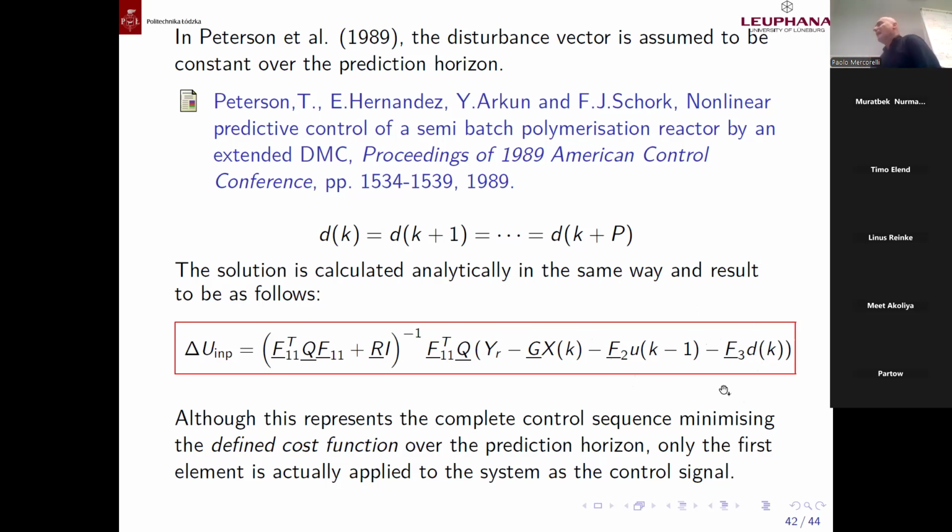This means the disturbance cannot be known, because otherwise it's not a disturbance. I can estimate it with an observer, with a Kalman filter for this. And then I can apply this. Really, it depends. If I want to, let me say, at least mathematically cancel totally the disturbance, I need this.